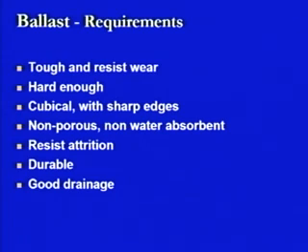The good drainage property is required so as to remove the chances of flooding. If there are chances of flooding, then it may take the material along with it, or there are chances that slowly and slowly the material will lose its strength. In both the cases, the track will lose its strength and it is going to be harmful in terms of the stability of the track, and there are chances that any mishap may take place as soon as the heavy loads start passing over such types of sections.